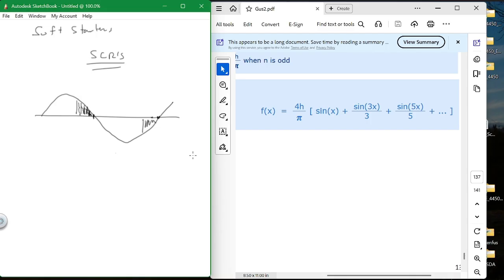And I had a guy that I worked with, who asked, are there examples of things where you adjust the speed at a later date? And there is. With the ovens at Owens Corning, if you heat an oven up to 400 degrees, it's less horsepower once you get the fan up, once you get the heat up to 400 degrees than it is when you're at ambient. So in order to heat the oven up to 400 degrees Fahrenheit, this is where